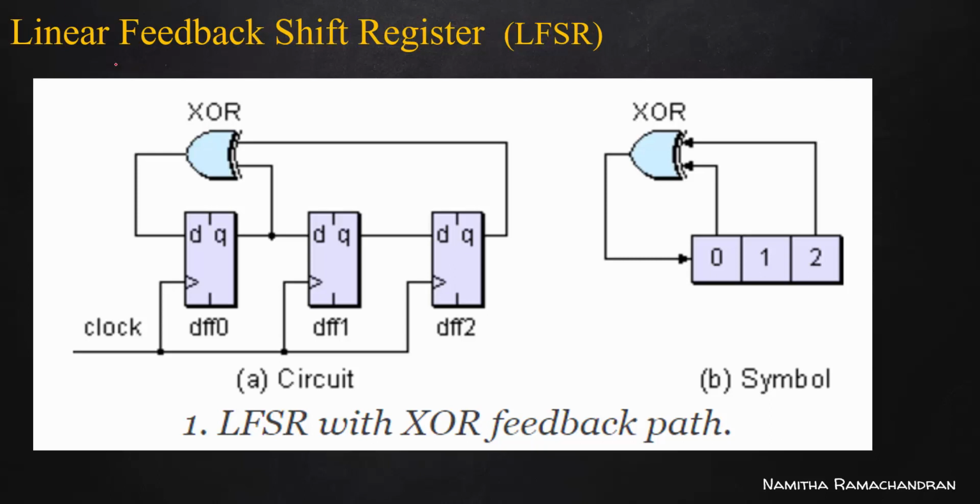Here we use the property of the XOR gate. Along with your shift register, we have to use XOR gate functionality. So here it is a 3-bit linear feedback shift register. We need 3 flip-flops in sequence with the same external clock pulse in a synchronous fashion. And here we can take the outputs of any 2 flip-flops as inputs of your XOR gate, and its output is connected as the external input to your first flip-flop.